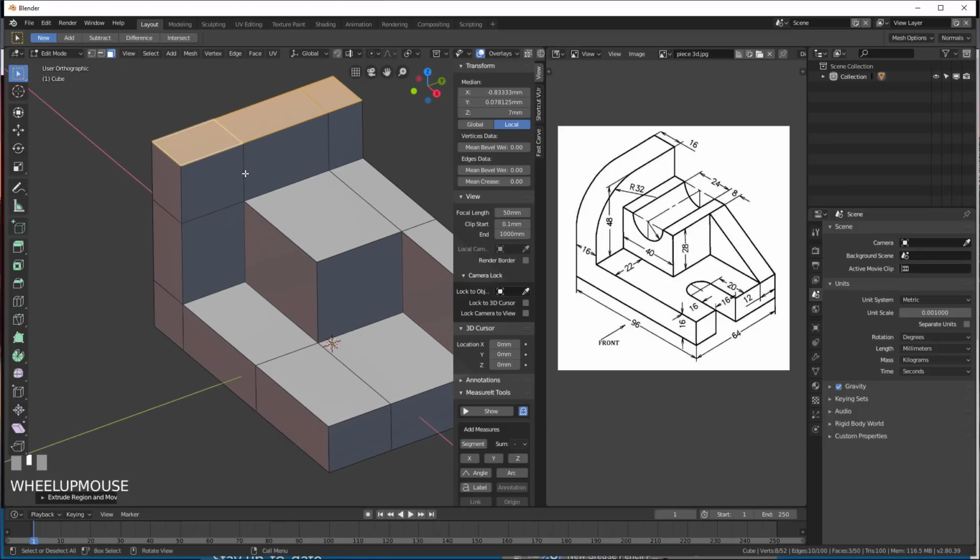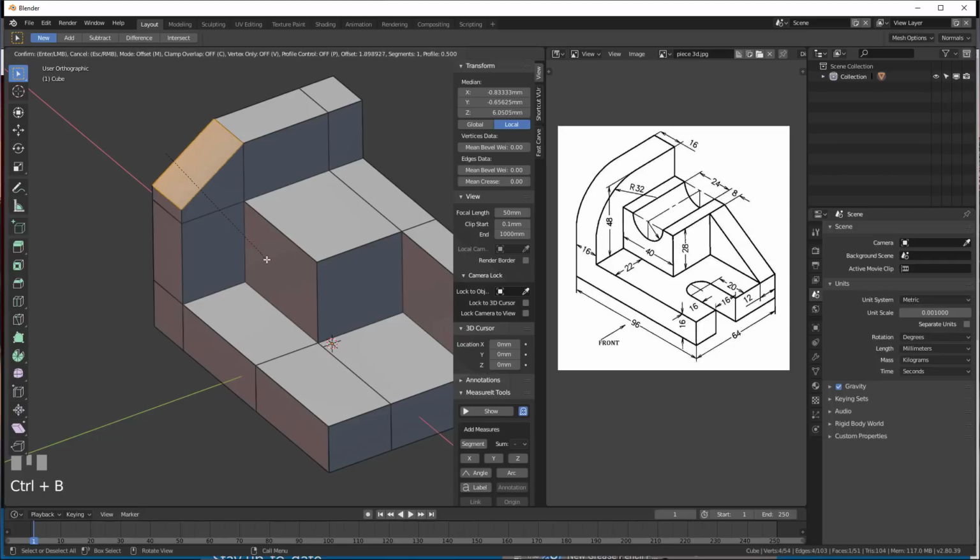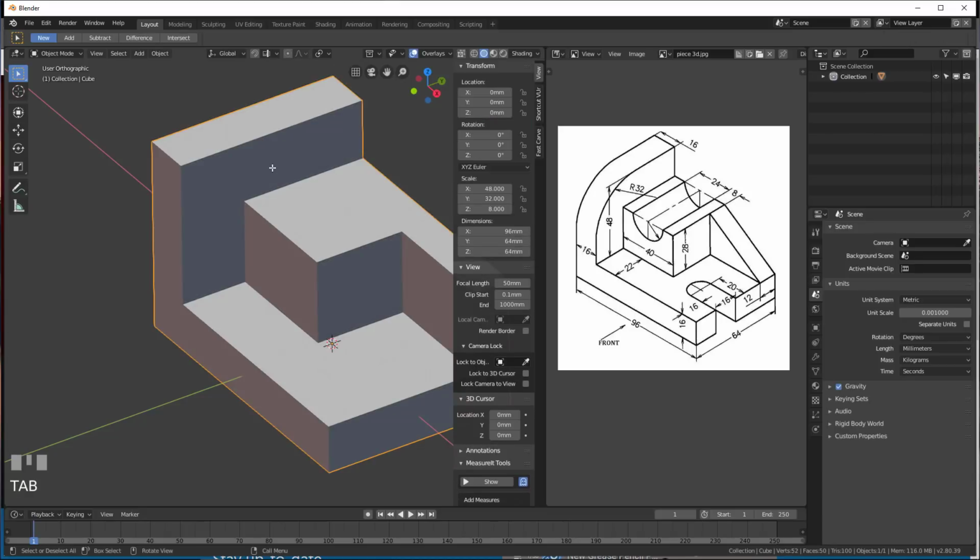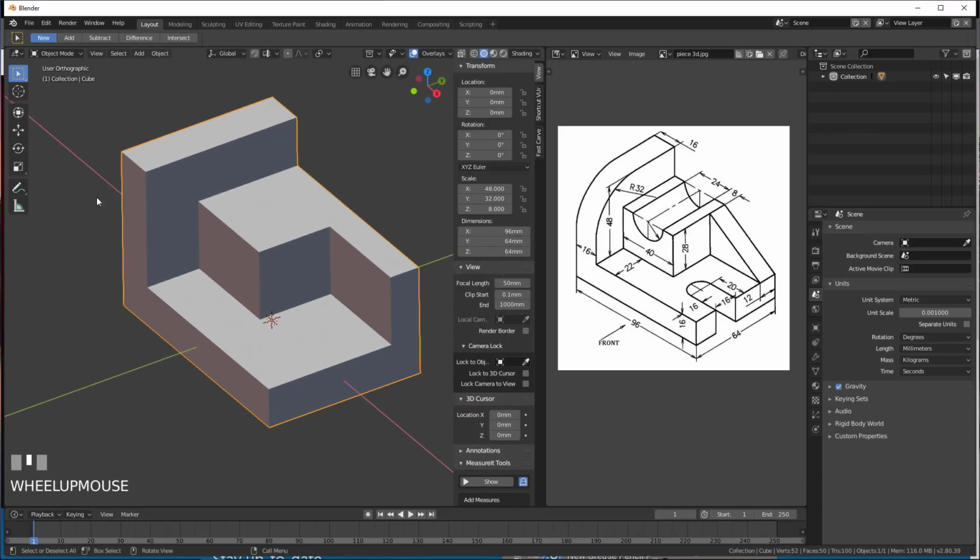And to make this, we have 2 things to manage. So let's go into edge selection. I will just select this edge, and with Control B I can add normally a bevel. But we can see that the bevel doesn't work well, and why it doesn't make a 45 angle, and if I just do a little movement it will go really wide, so I don't know why it isn't working. And it comes from this because we did scale our object in object mode, and actually it's really something